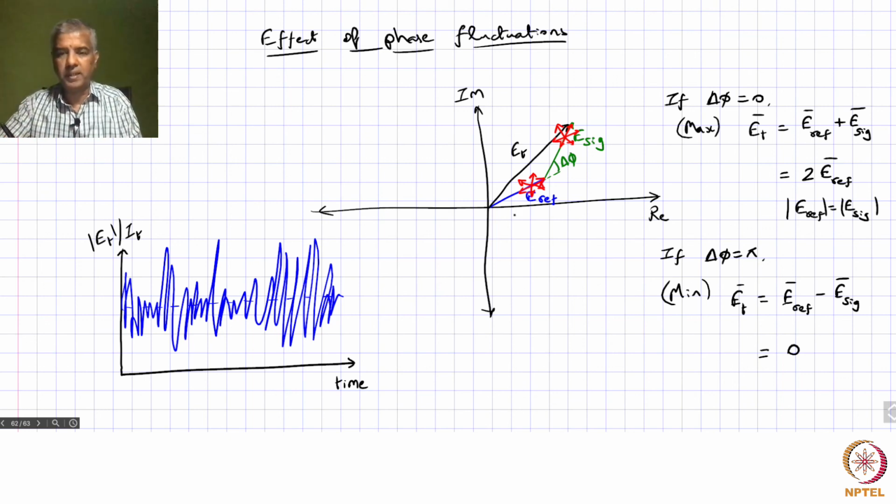And we are representing this at only one frequency. Remember, the phasor representation is typically at only one frequency, but the noise that you have tends to be white noise, okay? And because of that, there is no specific frequency here. It's a wide range of frequencies that contribute to this noise, and this is actually the problem.